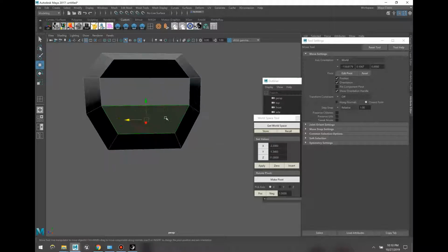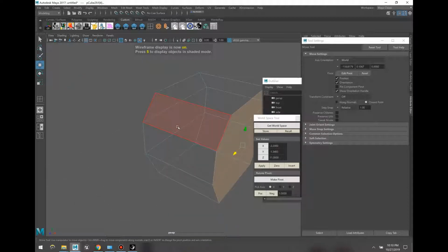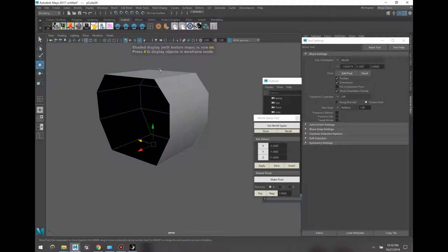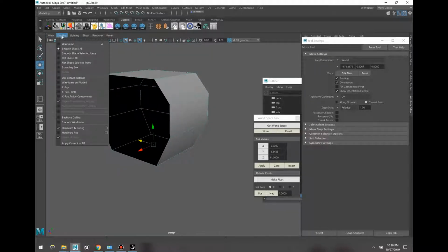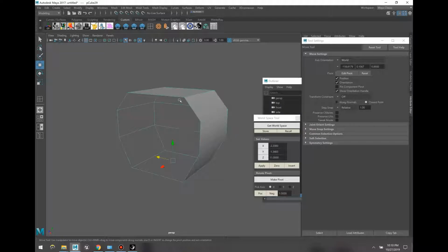And punch a, got one too many faces here. So I'm going to punch a hole in it, and then you're going to say to yourself, hey, it's hollow inside. So the trick to that is, one, to make sure you have backface culling on, so it's only rendering the side of the face the normal is facing. So you're going to say, oh, we want this flipped.